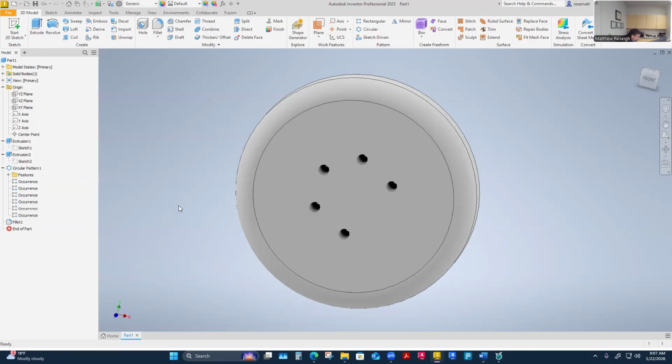And I have worked with people where that is one of their ways they work. I guess the part itself is still keeping track and logging that data, even though it's suppressed. It shouldn't show up on a cut file if you would like to export this file to a laser cut, but it's something that may show up if you change the file type, even though it's suppressed in Inventor. Will it potentially show up in a CAD file? I don't know. So I feel like we avoided suppressing stuff.